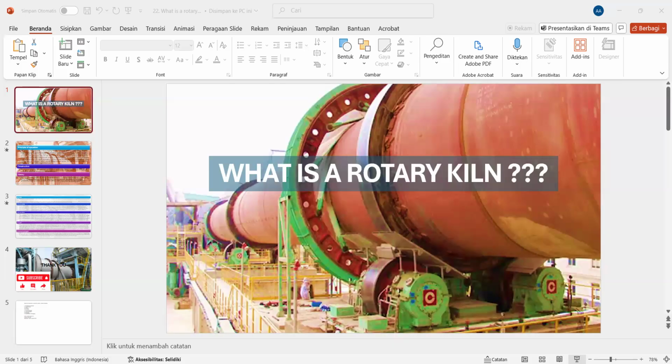Drive: the kiln is usually turned by means of a single gear surrounding a colder part of the kiln tube, but sometimes it is turned by driven rollers. The gear is connected through gearing to a variable speed electric motor. This must have high starting torque to start the kiln with its large eccentric load. A 6 meter by 60 meter (20 feet by 197 feet) kiln requires around 800 kilowatts to run at 3 rpm.